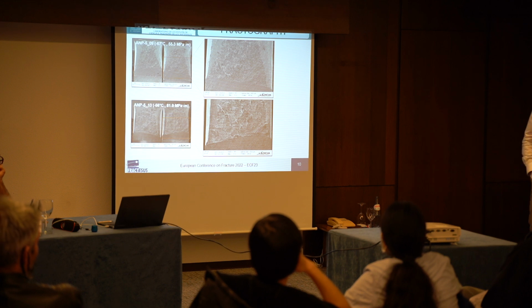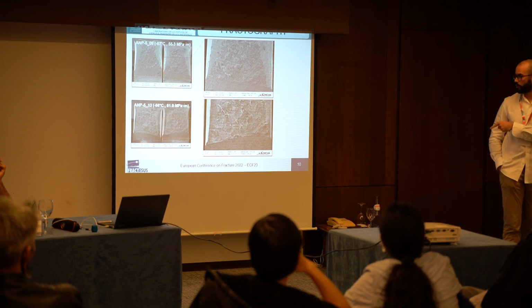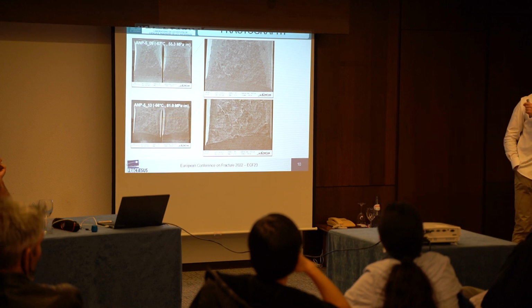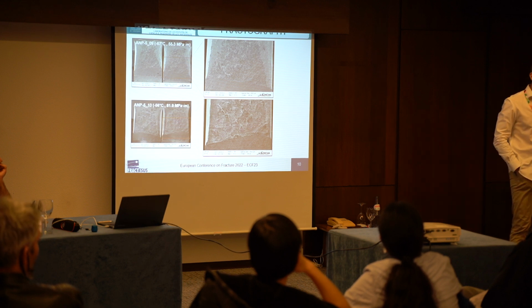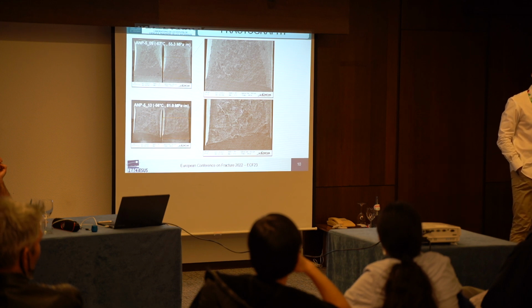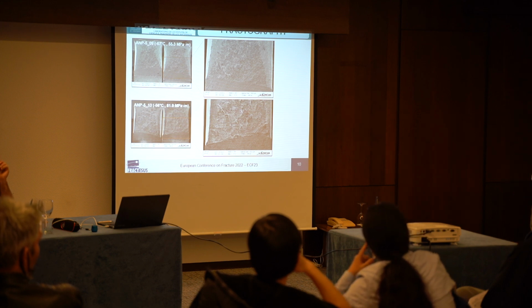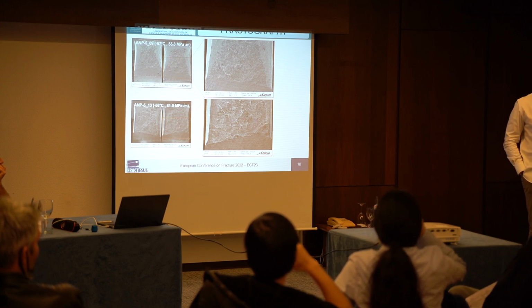If you can remove that slanting on the side, that's one thing to do. In practice, we are not using the side grooves because it was demonstrated that in these really small mini-CT specimens, the impact was very small. But it can help you satisfy that criterion in terms of crack front straightness. That is one thing.